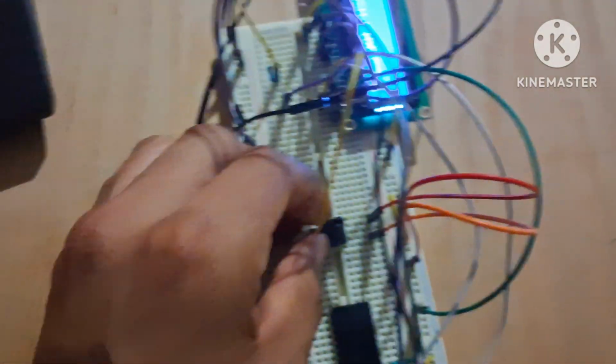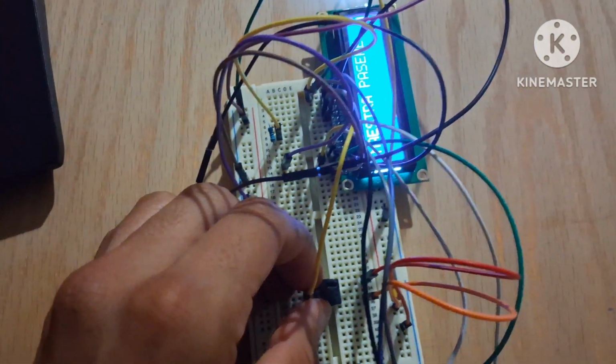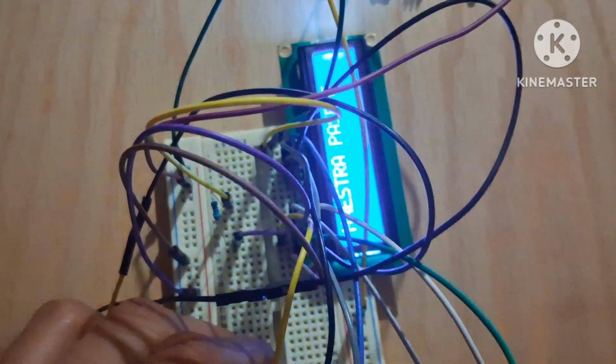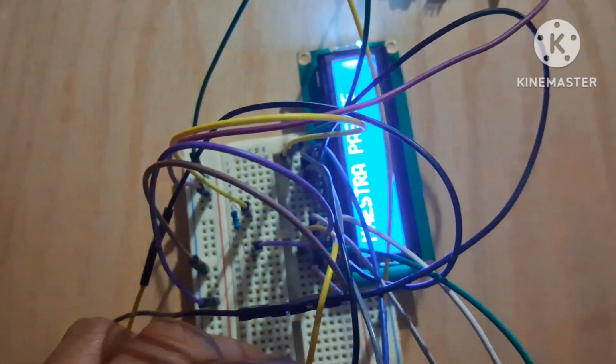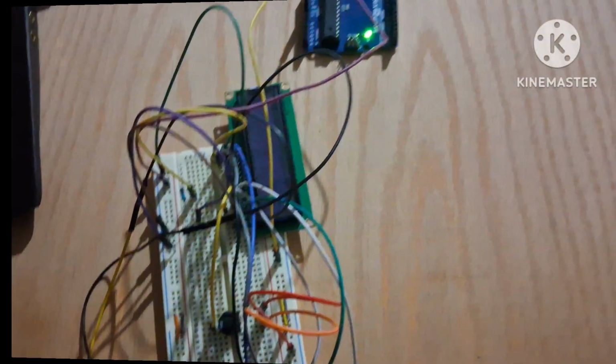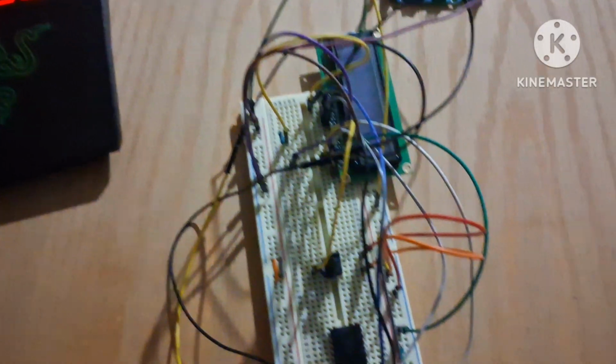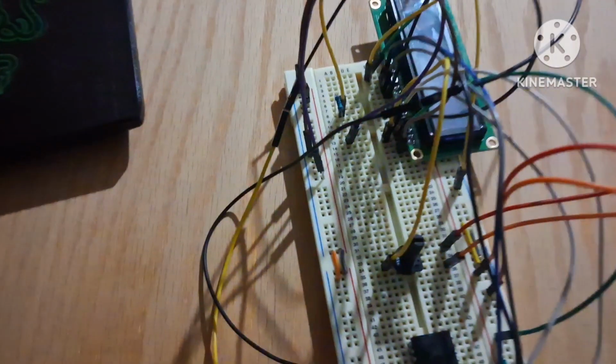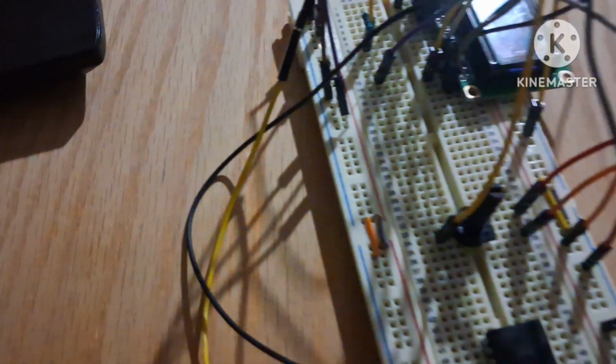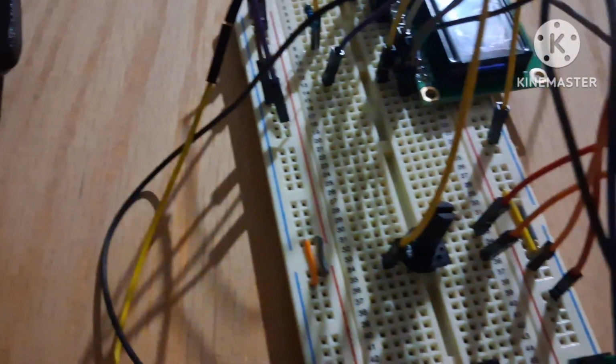One of the most common errors is not using a potentiometer, or poor calibration of the screen contrast, showing an unclear or at most invisible message. Another error is that the breadboard might have a false contact, or the cables might not be connected correctly.